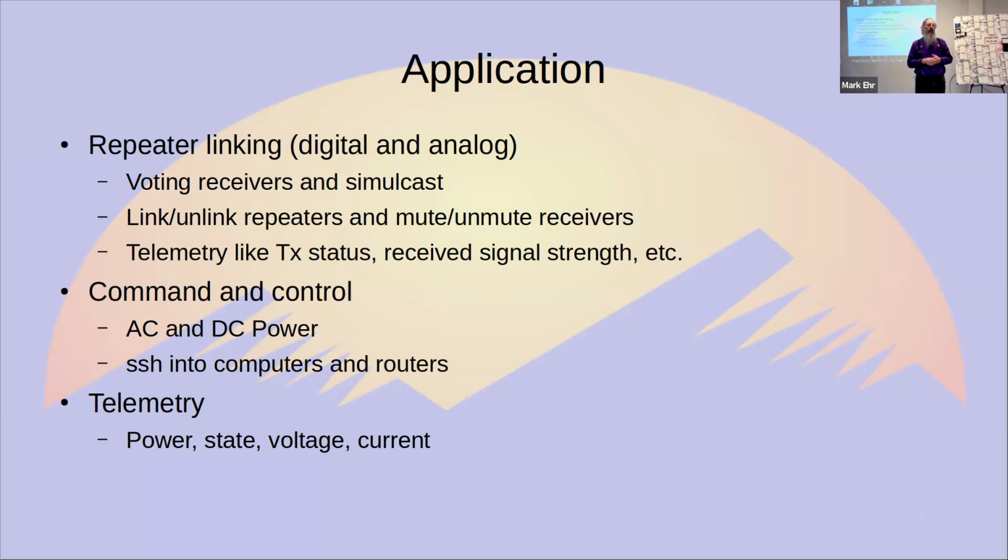Of course, depending on where you are, running this just in the ISM band is also not a problem because it's really RF quiet. But if you're at a site like Florida Mountain, where you can see the entire Front Range and every Wi-Fi router in the 5 gigahertz band, there's just a tremendous amount of noise. So being able to run that in the ham band makes a huge difference. With a radio like this, I think our longest shot is 75 miles.